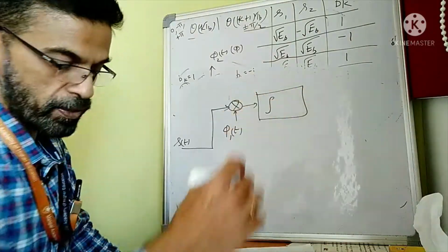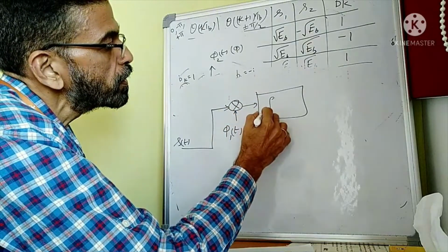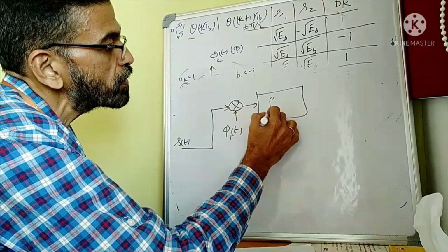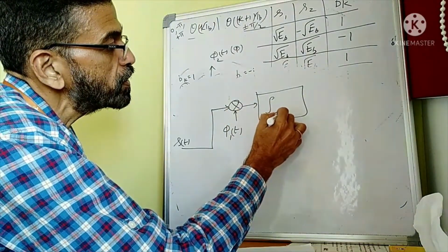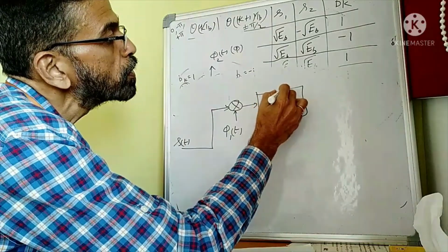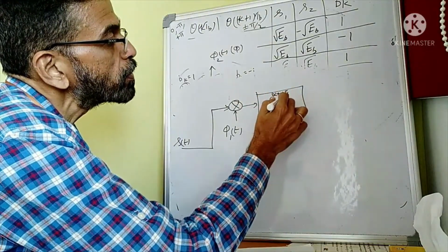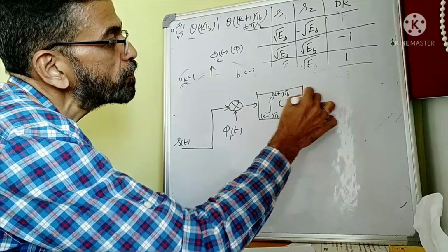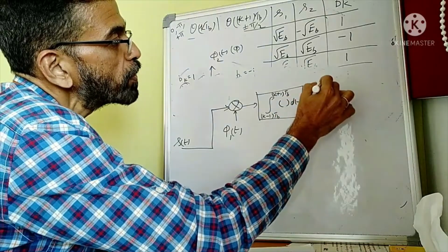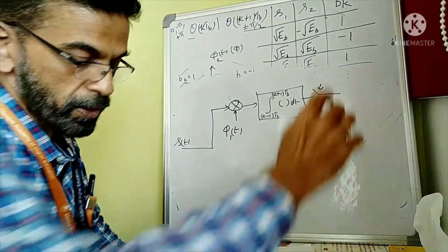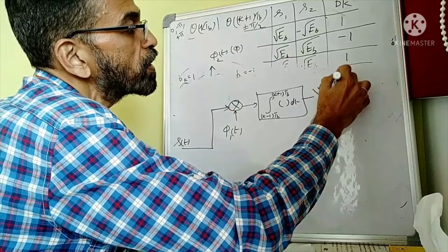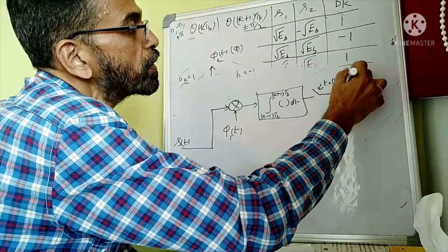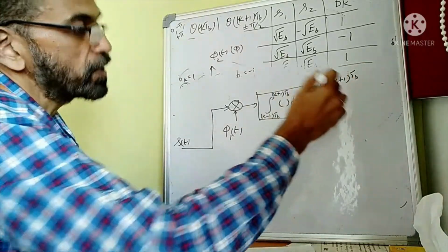Integrate the product in the interval k minus 1 tb to k plus 1 tb, sample at the time instant k plus 1 tb, which is the end of the integration interval.